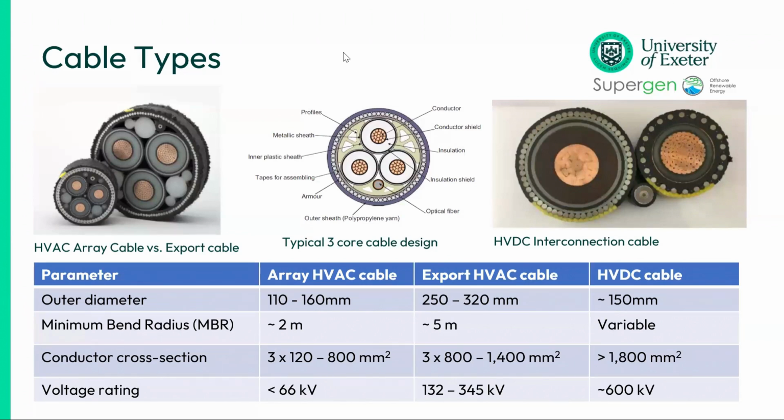But yeah, all of those need to be assessed, and need to be modeled as well. Torsion, if that's correctly designed, shouldn't be an issue. Dynamic cables will usually be torque balanced, so you shouldn't have too many torsion issues, unless, of course, the hang-off isn't correct. Then you have issues there as well. And generally you need to avoid compression for all of those cables.